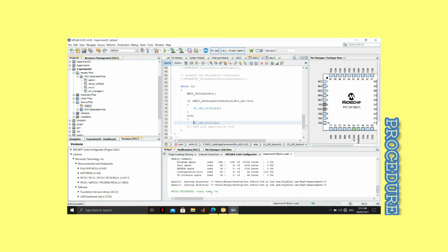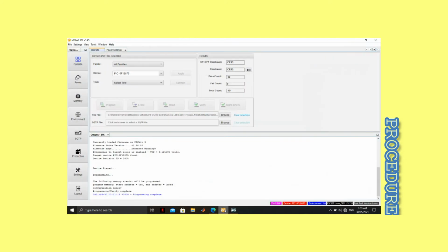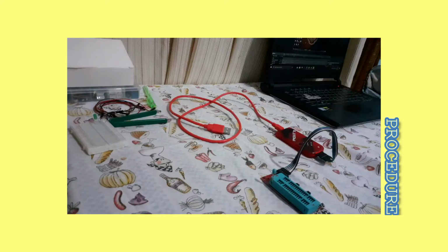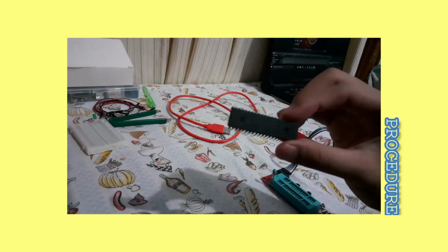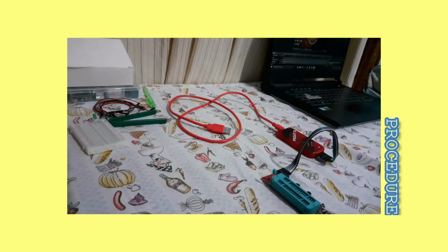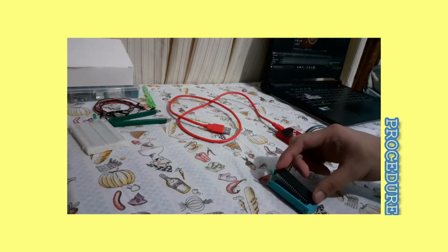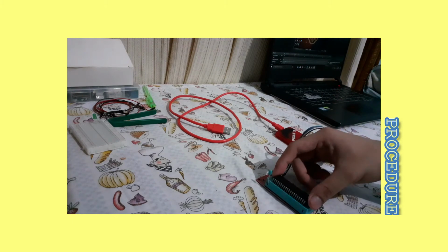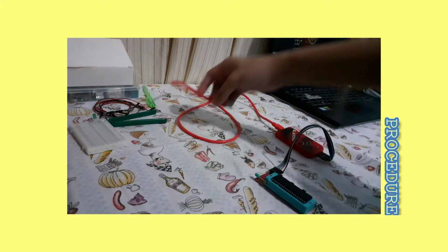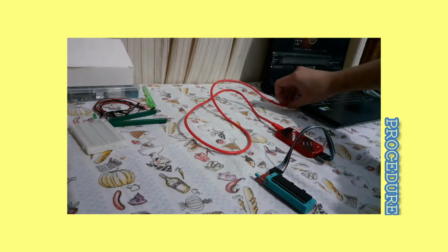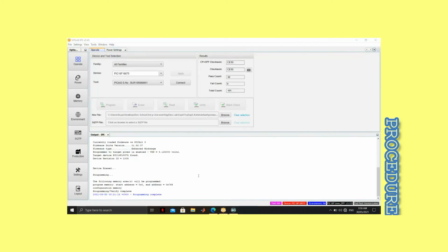After build is successful, go to MPLAB X IPE and connect your microcontroller. So now we would be connecting our microcontroller to our personal computer using our kit. There. Now it is read by the system. So now that we have connected our microcontroller, click connect.